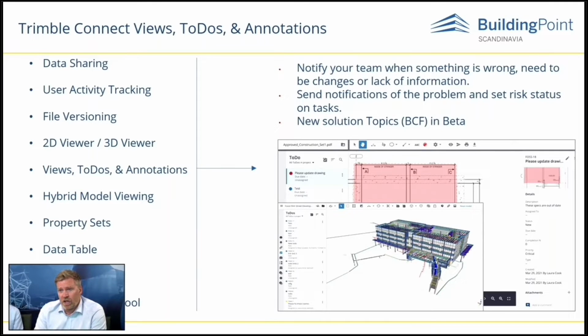In short, it is to set up information connected to objects or coordinate points in a model to communicate with other systems, our programs or other BIM software, essentially. BCF is an open format for issues. So when you create an issue that is model related, the BCF will retain where in the model the issue is related. So you can export it out from Trimble Connect and into other BIM tools using the BCF format.